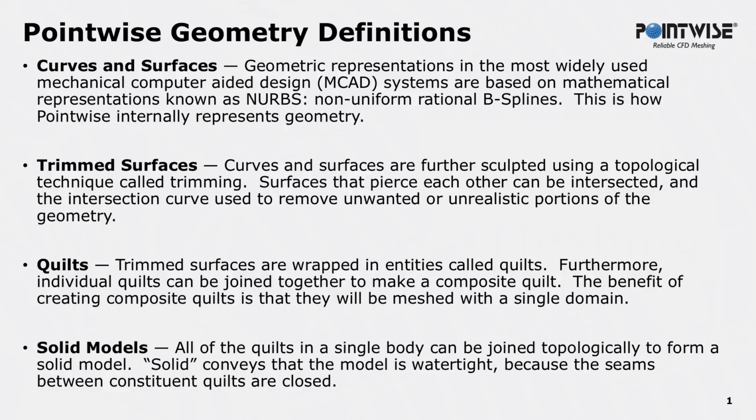As a first tip for users who create their own CAD and have control over how surfaces are created, consider that the model may be used for CFD or FEA simulations and decrease the tolerance used to define surfaces in your CAD tool accordingly before the model gets created and brought into Pointwise. This can really help you save time performing geometry cleanup prior to meshing. For those of you who receive their CAD from an external source, don't worry, we have more tips for you to come.